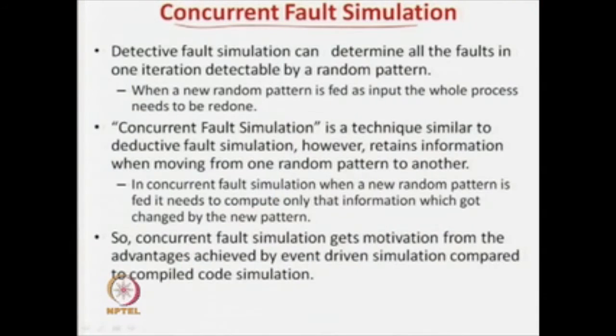So, the last fault simulation technique we will study today is concurrent fault simulation. It is the same thing as deductive fault simulation, in that in one scan of the circuit you find out which faults will be detectable, but at the same time we are not going to throw away the results. If by applying one pattern we find that these faults are detectable, we do not eliminate all the results. We apply another pattern and recompute only those things which are getting changed, that is event driven simulation. So, you can think that concurrent fault simulation is event driven simulation plus deductive fault simulation. That idea you have to feel.